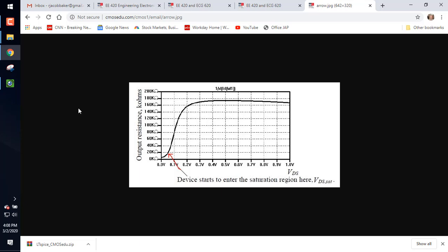See the arrow? See how it's behind here? It needs to be brought to the front and then pointed up. And this says that if I increase the VDS, what happens to the output resistance? It goes up. So that's why I use a larger length device there as I push it further up into this area right here. Any questions?